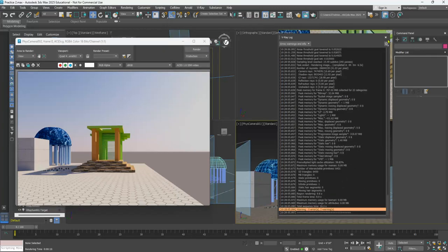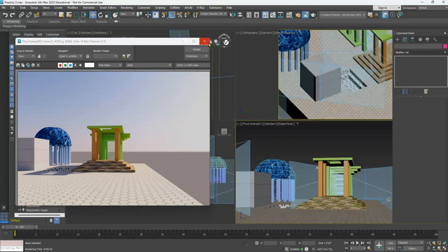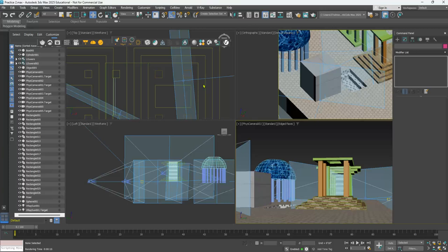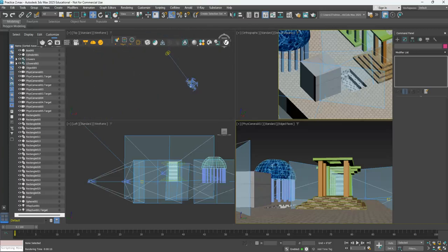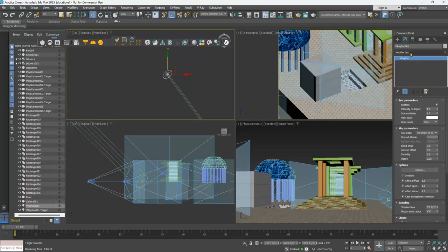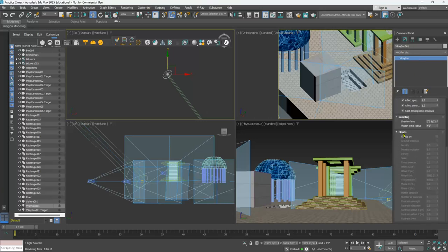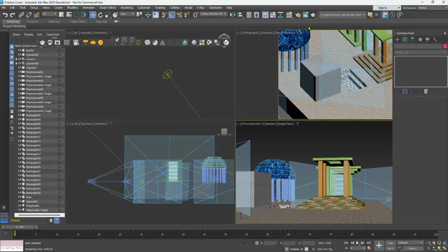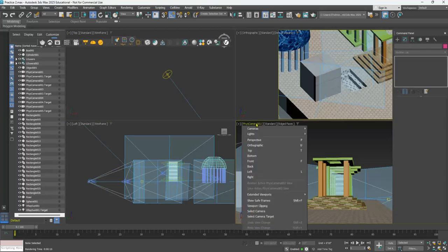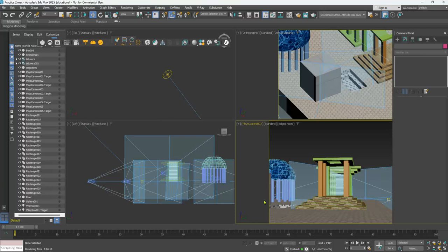We are able to create realistic clouds here. So if you go to the sun, find your sun here, and just click on the sun tab here, and then go to the properties here, and then move down to where it says clouds down here. I'm gonna turn clouds on. Again, we have all these parameters, but for now, just turn it on and render again. Let me first of all set up my save frame and render.